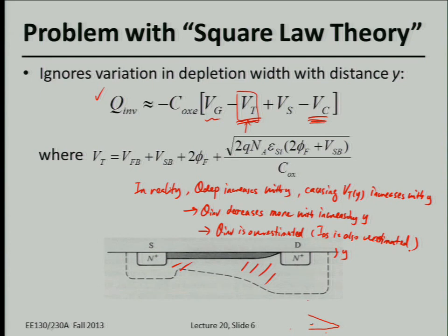So also, that tells us something about the mechanism by which the MOSFET saturates at a pinch-off state, okay? Let's talk about when you apply a high enough drain bias and generate a large enough depletion area or high enough depletion charge, okay? Then you won't have any inversion charge forming at the surface of the MOSFET, right? That point is what we call the saturation edge, right?